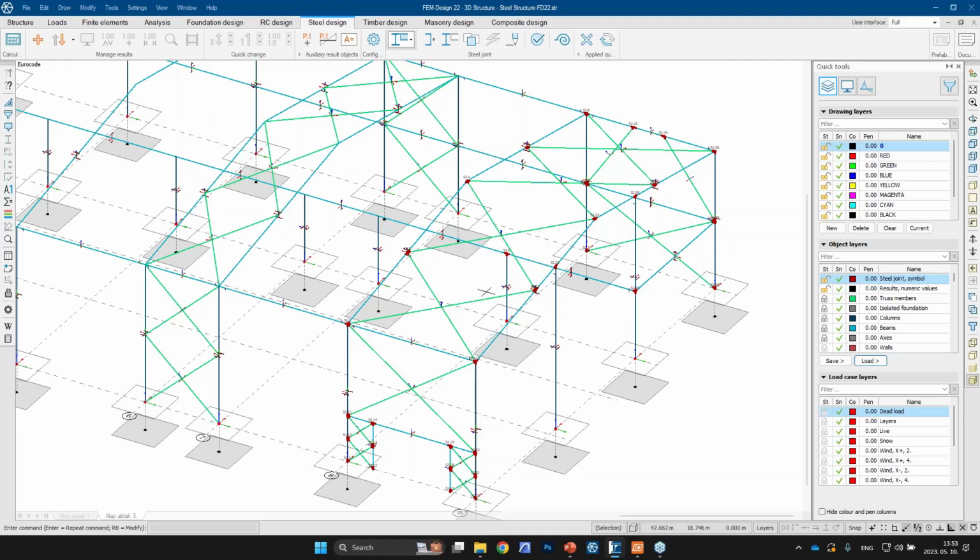And as I already mentioned, I can use 2 ways to share the model. There is a so-called live connection or direct connection if both programs are available on the computer, or I can use a dedicated file, SCF, in the background if 2 programs run on separate computers.